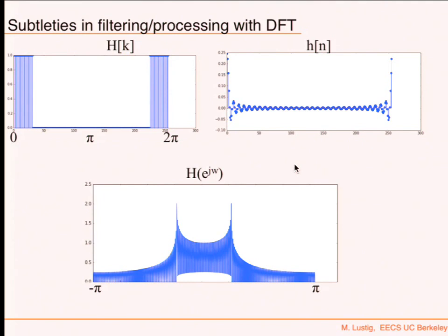One of the things you need to understand is that you cannot do a zero delay filter that has a really nice frequency response, because this is in fact a zero delay filter, since it's mostly concentrated here, although it leaked over here, really far away. But the idea was, because this is real, it shouldn't have any delay. If you had a pure low pass filter, it should concentrate around 0 and it would have no delay.